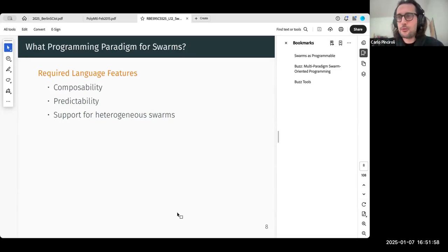We use tools that we don't understand. All right, so ROS at its base is a multi-process system, which means that you don't control the ordering and the scheduling of the processes, because that's done by Linux. If you run the same ROS code base twice and you find a bug in one run, if you rerun the same Gazebo simulation, you might not find that bug ever again for the rest of your life.